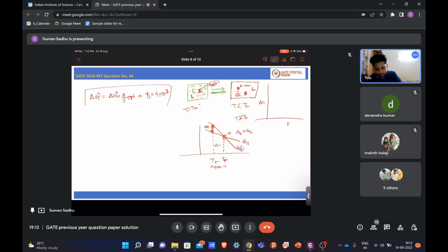So now you have two terms here: the volume free energy and the surface energy. The volume free energy is your driving force, so it is assisting nucleation. But the energy that is required for creating a new surface is opposing you, right?